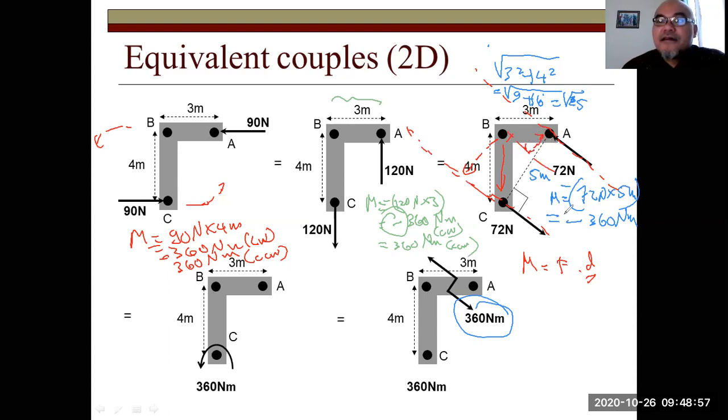Okay. You can calculate also based on this. You can calculate 72 Newton here, negative, multiplied by this distance. You need to calculate later using Pythagoras theorem what this distance is. Then multiplied, plus negative also, because this will also give a counterclockwise rotation about point B. This minus 72 Newton multiplied by this. Okay.